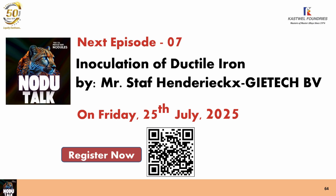So please pay attention. A pressurized pouring system is very good because it fills very quickly, but it's negative because the speed of the metal is very high when it enters your mold. With a non-pressurized system, the metal speed when entering the mold is lower. That's okay, but the problem is that your sprue is not filling.